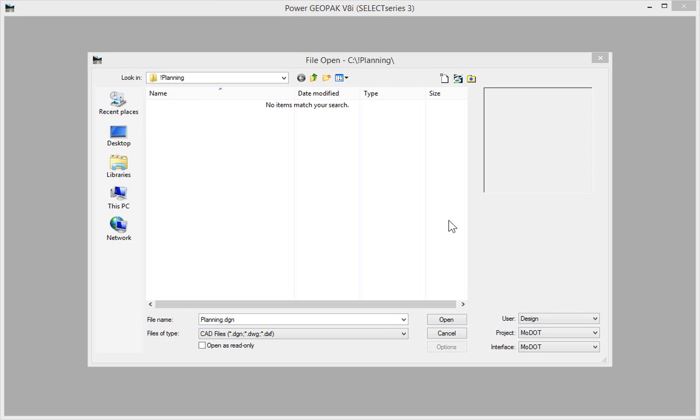We're going to make the assumption that the only thing provided for this particular exercise is a GEOPAK TIN file or a DTM file or LandXML file, basically any type of file that is providing existing ground data. So the first thing that I want to do is make a three-dimensional MicroStation file that we can import that terrain model information into.